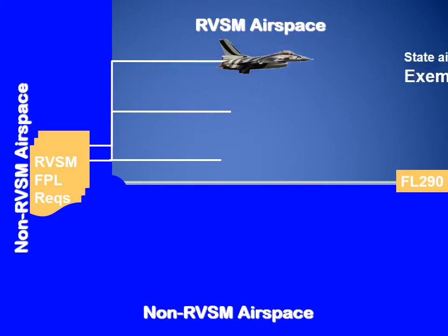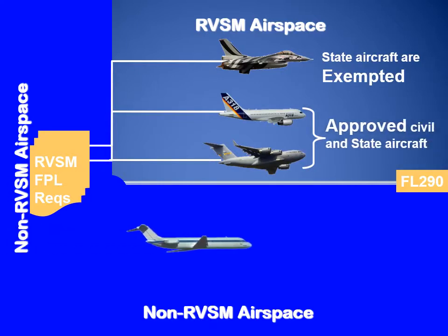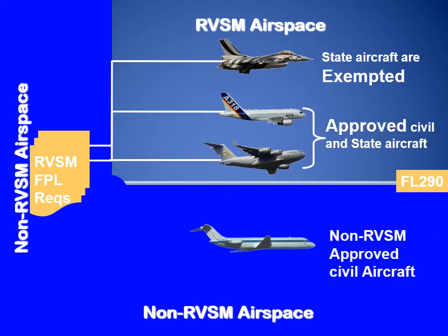Repetitive flight plans. All operators filing repetitive flight plans shall include in Item Q of the repetitive flight plans all equipment and capability information in conformity with Item 10 of the EUR flight plan form. When there is a change of the equipment or capability for a flight which is subject to a repetitive flight plan, a modification message for the day of operation shall be sent not earlier than 20 hours before the estimated off-block time.